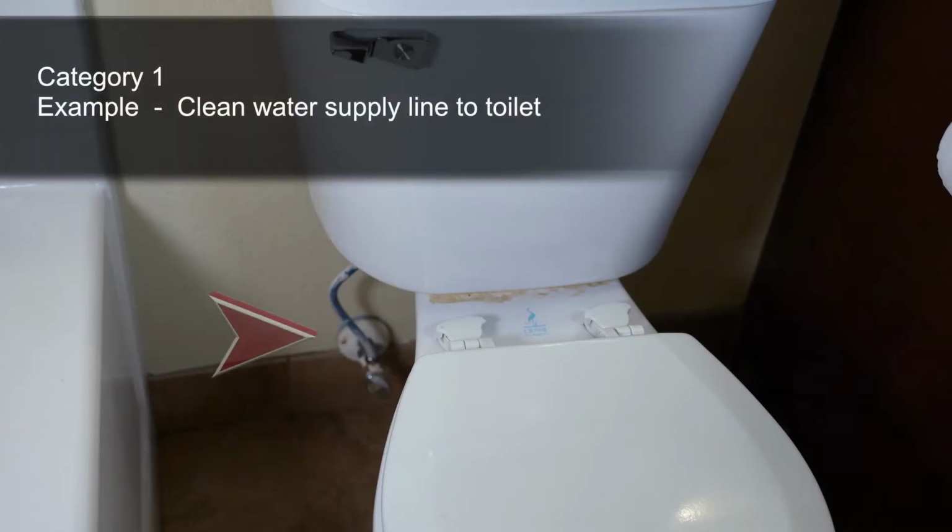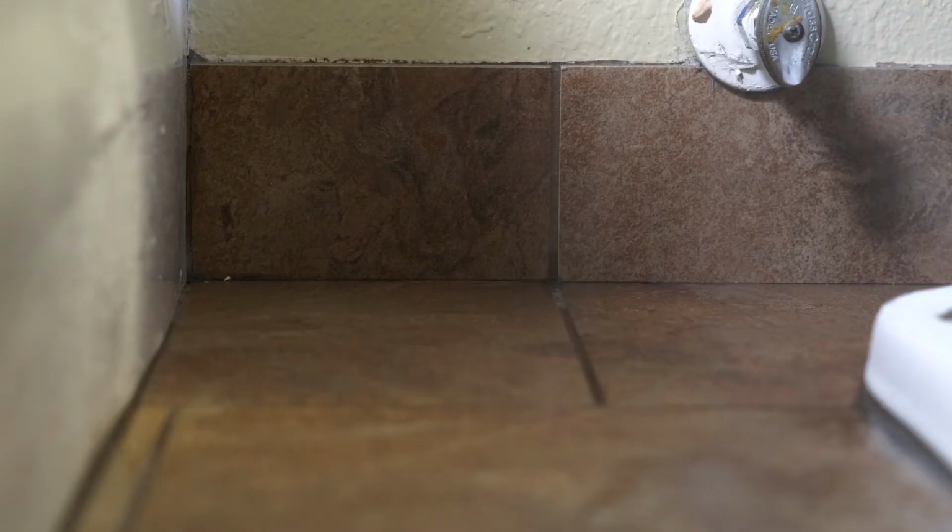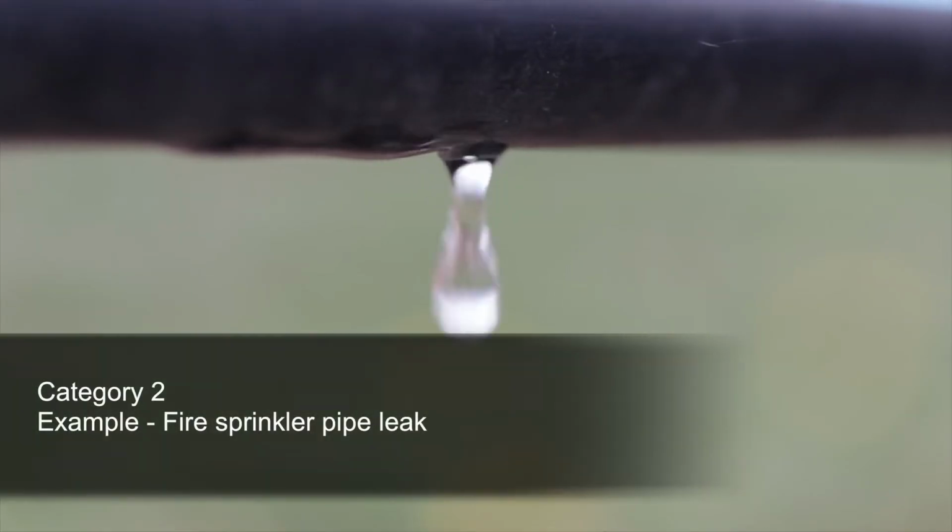Here are some examples. Behind your toilet is a water supply line, and that often breaks. And if that line breaks, it's clean water coming from the city pouring into the floor. Category 2 water examples might include something like your fire suppression line or your fire sprinkler line if it ruptures. It's water that's been stagnant in that line, but shouldn't pose any chemical or biological hazards generally.